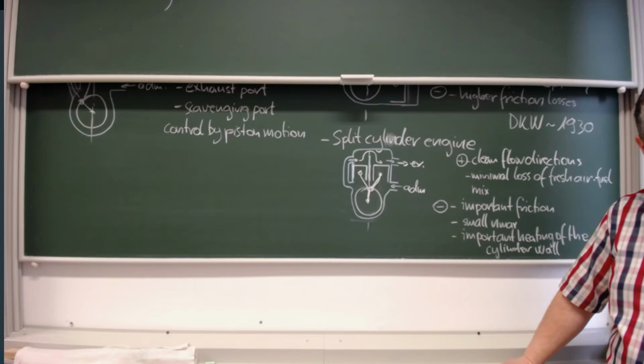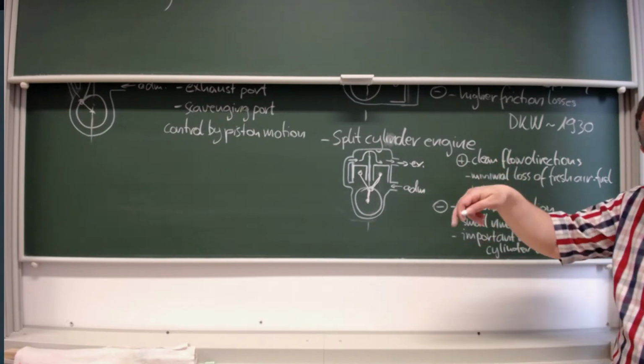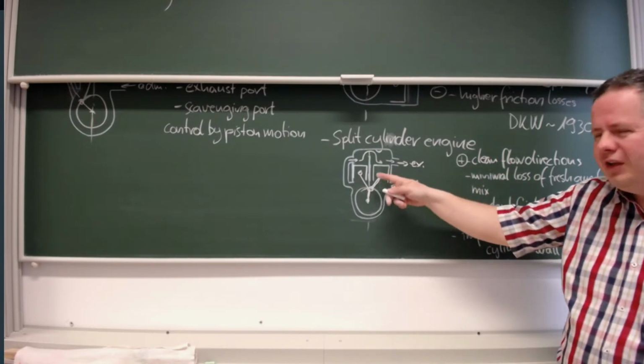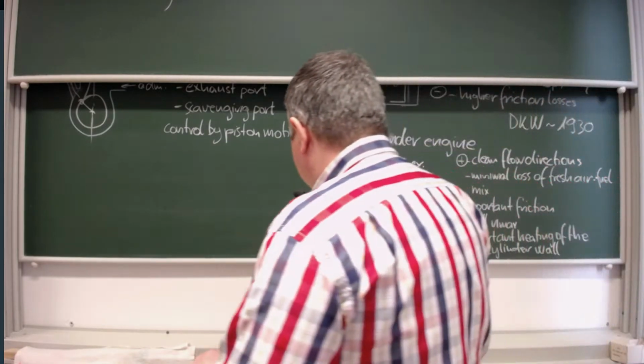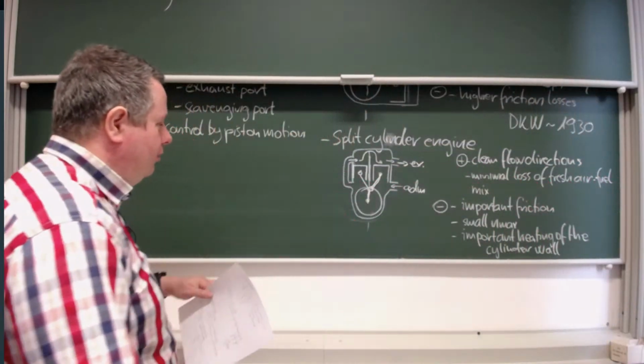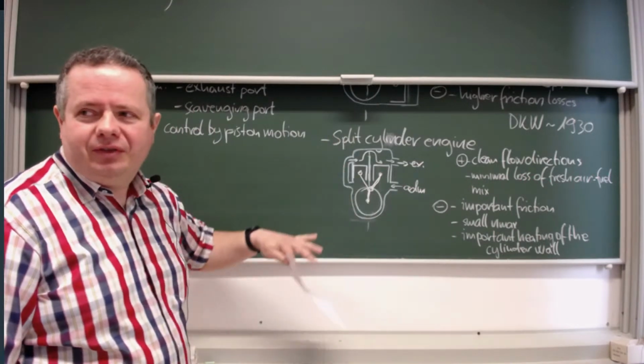Nevertheless, by the time the pressure, the power was not so important and the efficiency was more important at low RPMs, this solution was really, really popular. You get very nice cylinder castings. So 2 cylinders, 2 bores, and complicated admission and exhaust canals. So this was really an art in casting to make such cylinders in one unit.